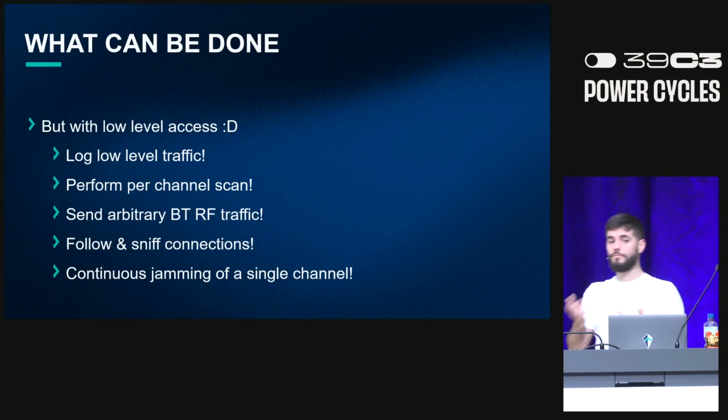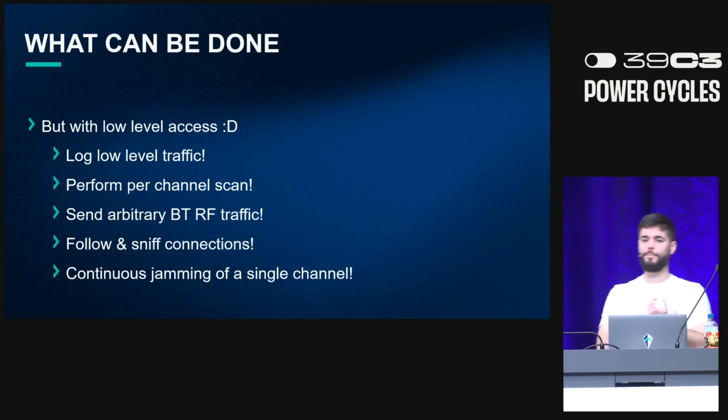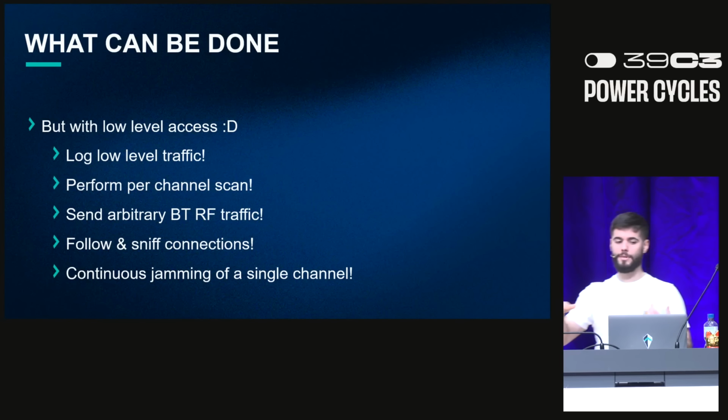So some things that we can do with this is, for example, log all the low-level radio frequency traffic to see if everything is compliant, or even if there's some unexpected traffic. We can perform per-channel scanning, which previously was not possible in the ESP. Now we can set a particular channel to scan on. And we can also transmit arbitrary radio frequency traffic with the Bluetooth peripheral.